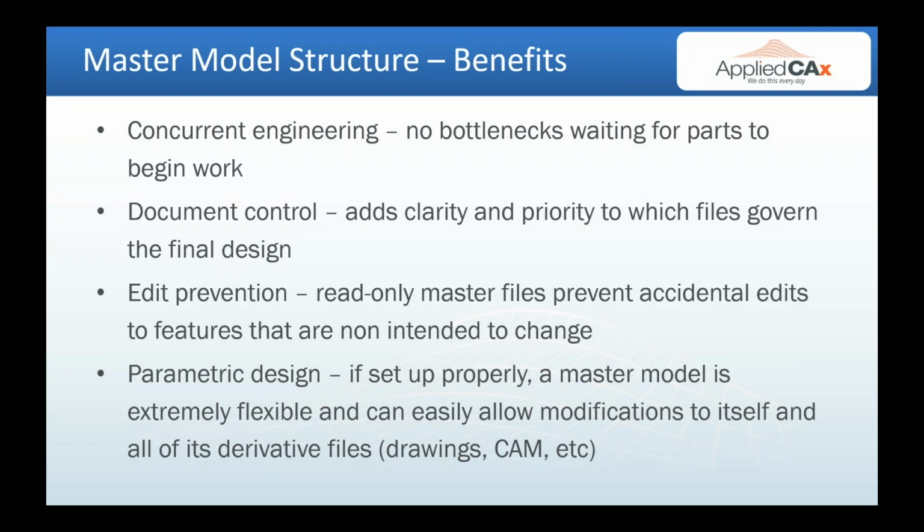It also is an approach that helps organize document control, adds clarity and priority to which files govern the final design. So you don't have to wonder if the drawing is the top level design or if the part file is the top level design. You arbitrarily decide, I have a master model, this controls the design. It helps control edits. It makes sure that master files and geometries are insulated from any sort of edits.